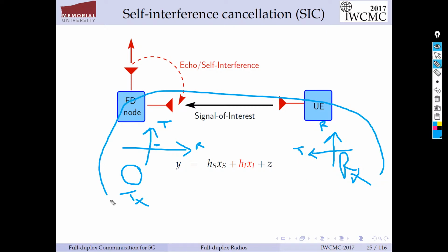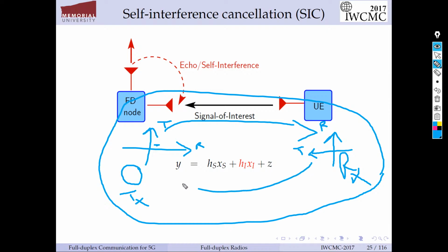And here the receiver uses this for reception and this for transmission. Now, since the environment is not rich scattering, not multipath, it does not cause any changes to the polarization of the electromagnetic field. Whatever polarization you transmit at the transmitter remains the same at the receiver. So to make sure you receive the signal in the vertical polarization, you receive at the receiver in the vertical polarization. And the same with the uplink. Let's say this is for downlink and this is for uplink.